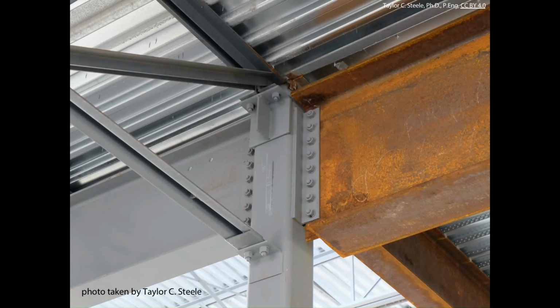Question? This might be a stupid question, but is there any reason for some of it to be rough steel that's not powder coated and the rest of the steel to be powder coated? Yeah, that's a good observation. So this is actually primed. So this is a primer. And this is unprimed or bare steel. Usually if you're going to paint it and expose it, you'll prime it so that the painters can come in and paint it.